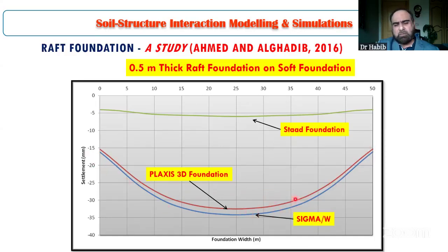If you recall the slope I mentioned for the maximum slope allowed for structural distortion, in this specific example the modulus of subgrade reaction concept has failed to capture that, while the other finite element based software are really capturing that concept. We can see the steepness of the slope over here. So this is how we can compare the empirical approach and real modeling in the software.